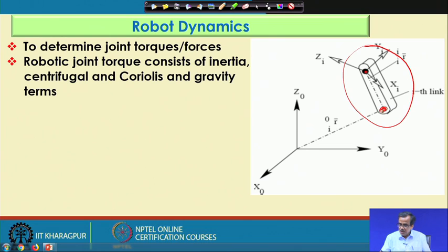Now, here if I put one motor, the motor is going to generate torque, and some angular displacement, velocity and acceleration. Now, if I want to measure that, I will have to measure the reaction torque. How to measure? To measure the reaction torque, I will have to concentrate on that other end, and that is why this coordinate system is attached here, but not here, and here the coordinate system is denoted by x i, y i and z i.